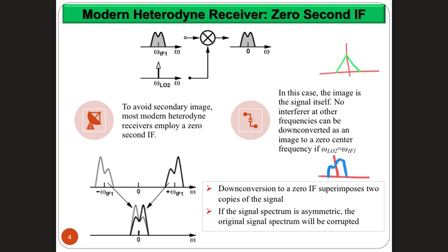Now, if you want to represent that mathematically, it will end up being a complex signal in time domain. But the whole idea is, even without adding a cosine and sine carrier, which is the more common case, FM modulation ends up producing signals that, when you take their Fourier transform and represent them in the frequency domain, will look asymmetric. They will not look symmetric. So they are complex by nature.